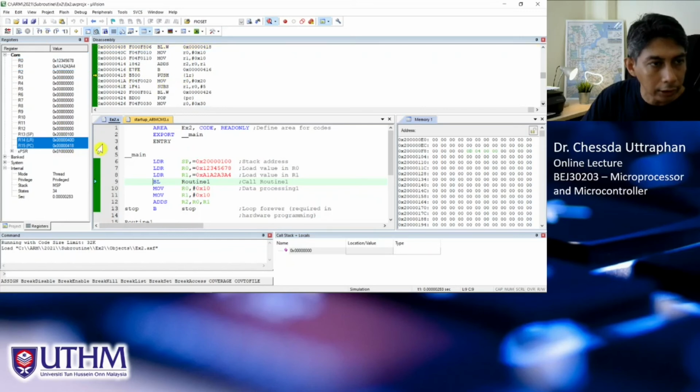We want to execute this 418, and we want to push LR into the stack. And we push. So now the stack pointer, look, it points to FC here, because this is 8, 9, A, B, C, and this is 40D. The value of LR is now in the stack safely, and we can execute the instructions here.